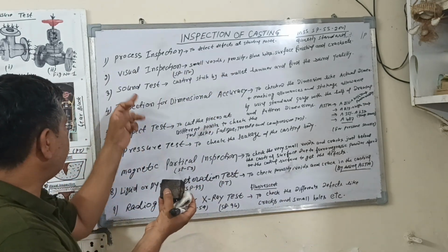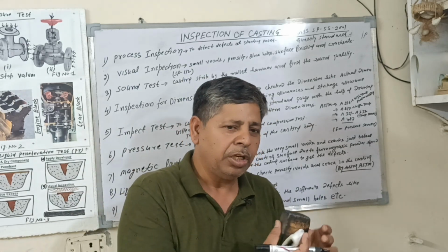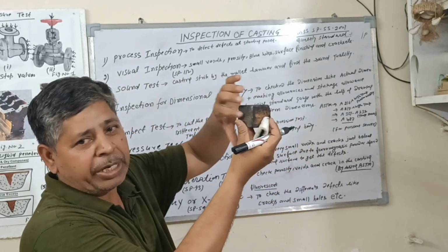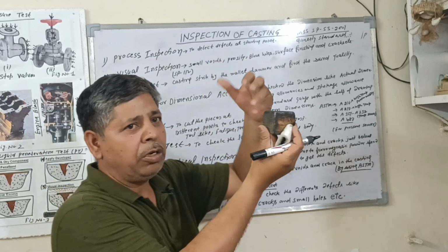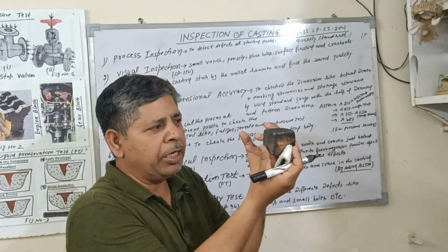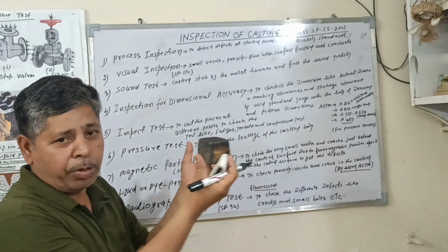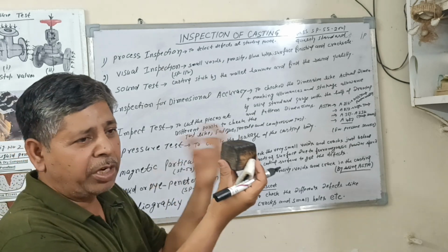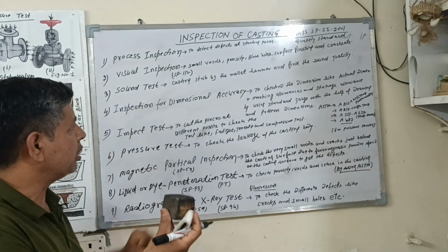Third is the sound test. This is a very simple test. The component is struck with a mallet hammer to get a high quality sound. A high quality sound means there is no problem and no defect in the component. So this is the sound test.